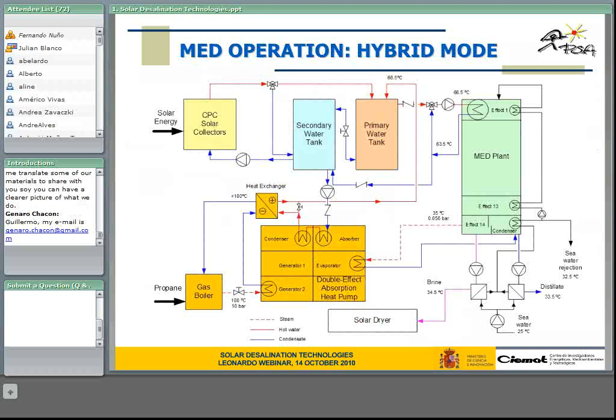The next morning, when the sun starts again, the temperature from the solar collector starts to rise to a certain level. We could reduce progressively the contribution from the gas system and introduce the solar until we completely stop the absorption pump. Depending on how we design the system, yearly, 80% of the energy could come from the sun, if we have a sufficiently large solar field and thermal storage, or just 10%.